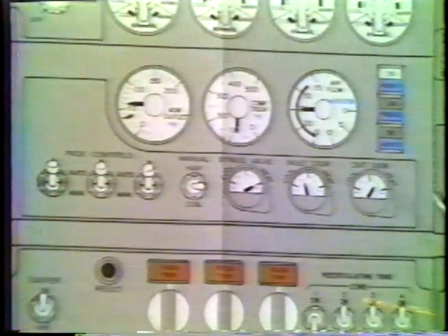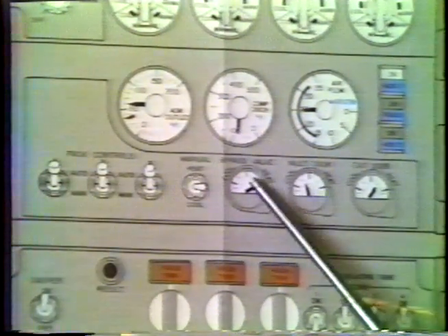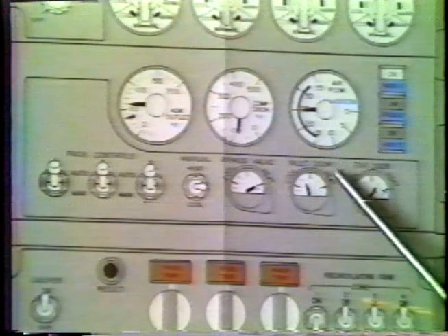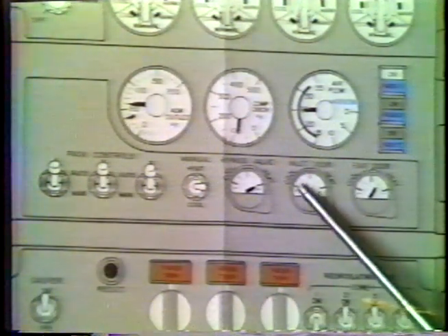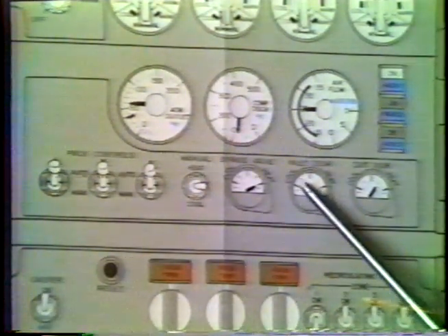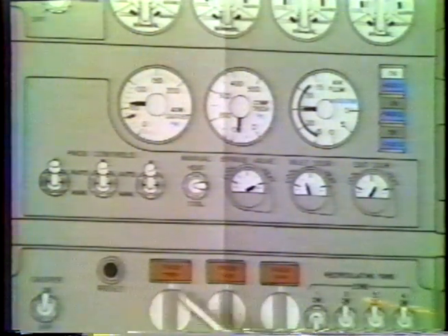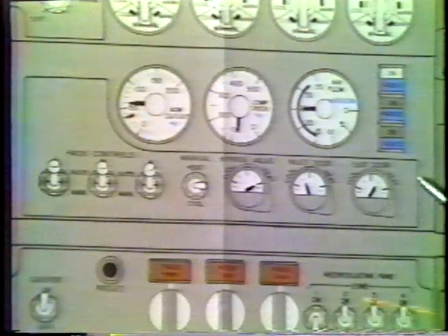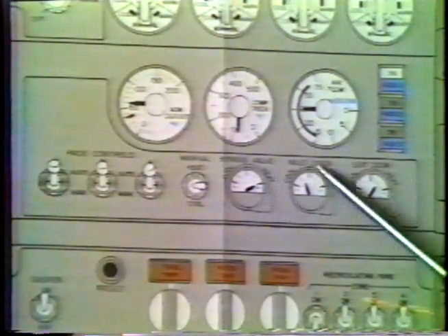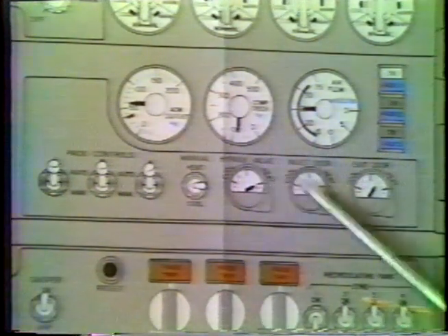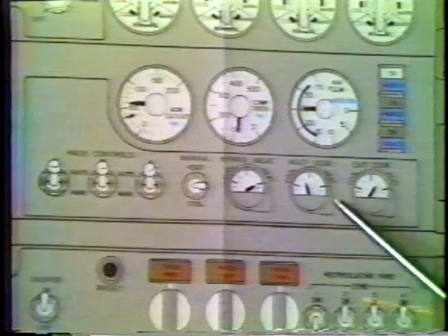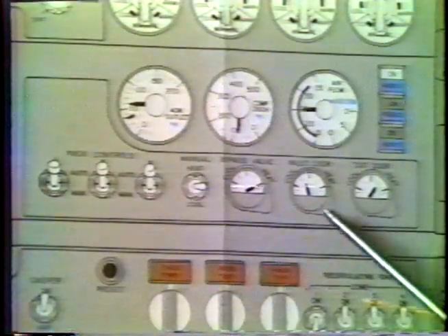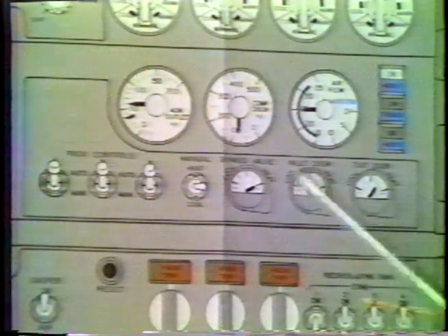Vice versa, if the bypass valve started going towards cool before the inlet gets to full open or cool, then that would be out of sequence and a pack will trip. Now, technically, I say full, there is a little grace area in there where they can overlap a little, although they normally do not. But when they get out of that limit, you will get a pack trip.